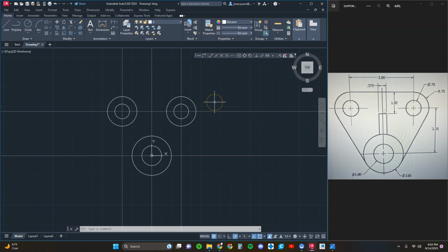So what I'm going to do now is I'm going to type L and hit enter. I'm going to pick tangent, and then I'm going to pick the outside here. Now you can see I'm attached, and regardless of what direction I go, it's going to keep my line tangent. Now the next very important thing is don't just come down here and think it's going to do the same thing, because it's going to snap to the middle by default. So if I go tangent again, just to say that's the only way I want to snap to something, you can see, regardless of where I pick, okay, and you do have to be careful. If I pick up here, it's going to make these tangent like this, but you have to be in the general correct quadrant, and if you are, you select here, you can see I now have a nice tangent line.